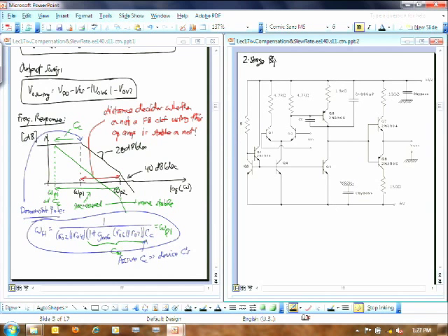Okay? First thing I guess we ought to do is just point out things you probably already know about your lab. You can recognize a lot of different parts of this thing. You pretty much understand how this whole thing works now, right? And so just to point out some of the obvious things, if you look at this right here, what is this? Yeah, you can call it either a current source, but I like to call it a V-bias generator, because what it's doing is it's providing that voltage V-bias that then is used for all the actual current sources that you have in this circuit. Okay? So that's your V-bias generator.